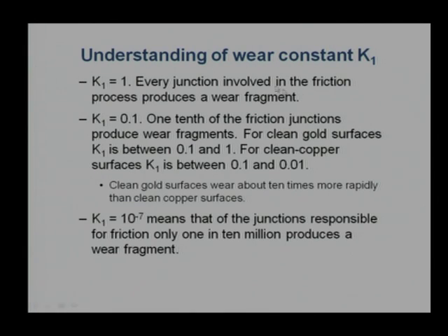And the conclusion from these two sentences is that a clean gold surface wears out about 10 times more rapidly than clean copper surfaces. We are using the word clean, assuming there is no contamination layer on the surface. There is no additional material, it is pure gold, no oxide formation, no lubricant layer, nothing on it, pure gold and pure copper.